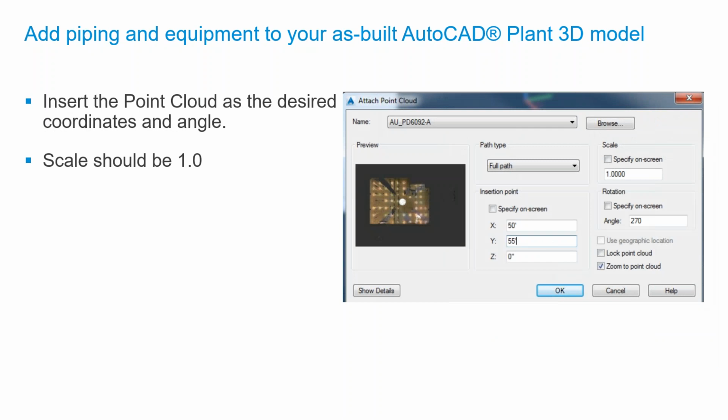While you integrate this information inside AutoCAD Plant 3D, be careful about the point cloud coordinates and the angles you attach, and also take care of the insertion points or coordinates of these scans. These are predominantly important when linking the existing scanned information to the newly created digital model. Scale is one more important factor when adding this information into the as-built model.